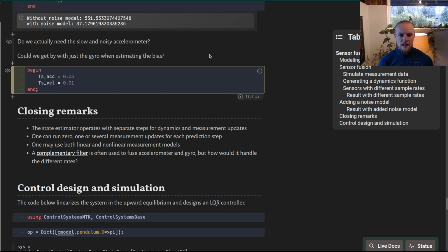We could actually say that this Kalman filter we have implemented here does implement a form of complementary filter due to the noise model we added. But it doesn't look like the traditional complementary filter, at least not superficially. So this is more of an advanced version of a complementary filter, if you'd like.